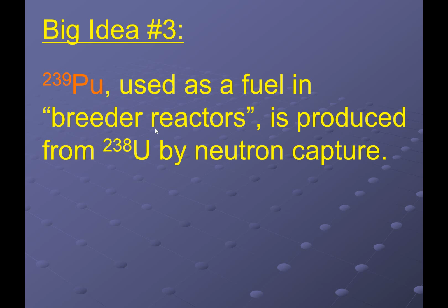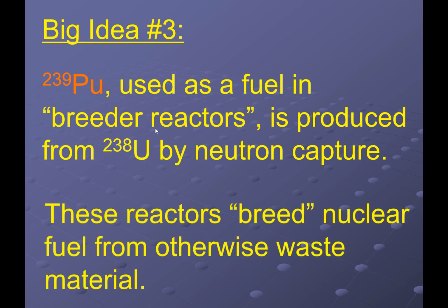As we step across some of these slides here, we're going to see some of the details. So the reason why these are called breeder reactions is because, first thing, the source is actually very plentiful because it's just a waste product out of my first power plant. But the other thing is this one will not require the same enriching that we're going to see for uranium that we need.